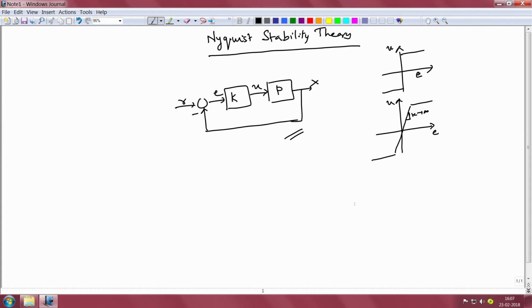So in the case of on off control, we would have the control law of the form u is equal to sign of E, where sign is the signum function given by sign of x equal to plus 1 when x is greater than 0, 0 when x is equal to 0 and minus 1 when x is less than 0. But this is not necessarily the only way in which we can implement high gain control. There are several other control laws that have been developed over the last half a century or so.